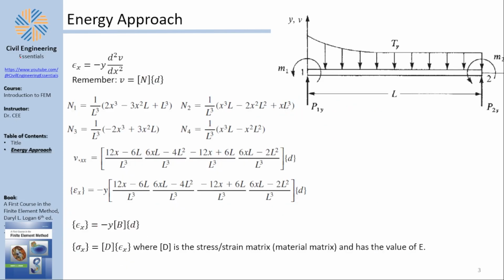And with that being said, I once again have to find V with respect to d1y, d2y, phi 1, and phi 2. I need to do this because I want to differentiate pi p with respect to those things. So that's why I always try to switch into the nodal displacements. Also, the stiffness matrix connects the forces with the nodal displacements. So it stands to reason to try to shift everything with respect to nodal displacements.